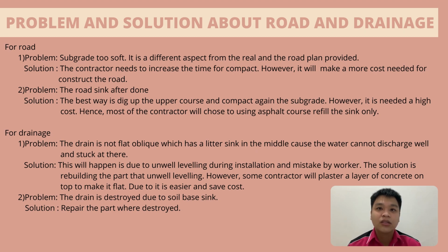the middle, which causes the water to not discharge well and get stuck there. This happens due to poor leveling during installation and mistakes by the worker. The solution is to rebuild the parts so they are well leveled.